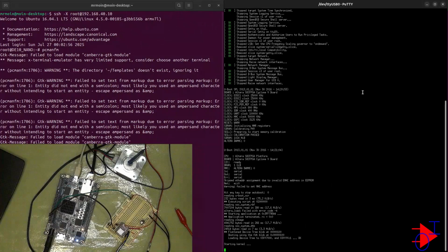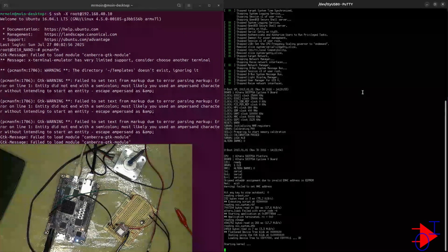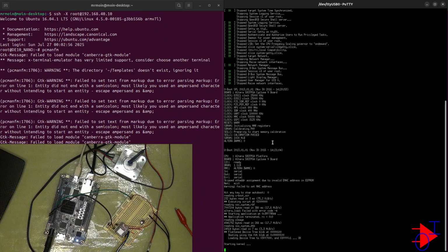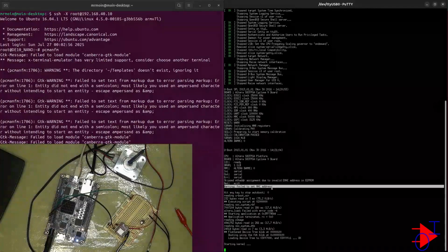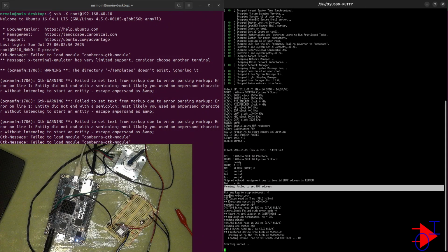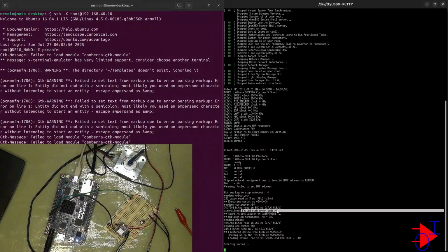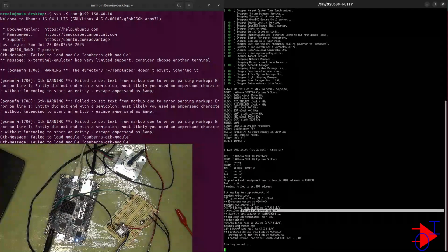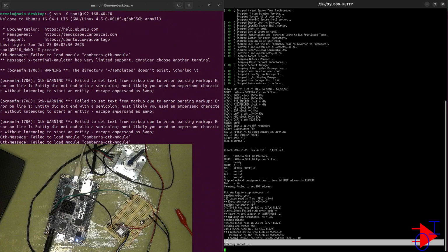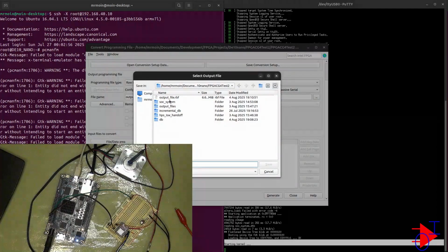Okay, so this is the point I want to demonstrate here. From the console connection, what you will see is that, hey, I'm rebooting, and it will say, hey, there's something weird going on, and it's trying to read the RBF file. This is our soc_system.rbf file. And it says, hey, I cannot load. And then it just basically halts. Kernel does not load.